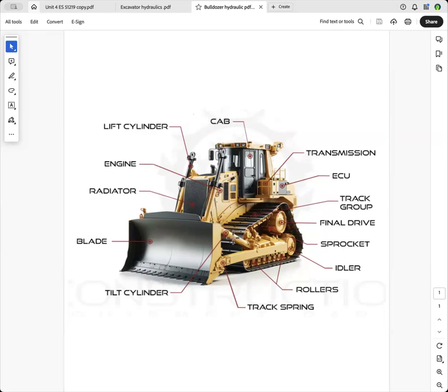There's a hydraulic cylinder here, which tilts the blade. There's a hydraulic cylinder here that does the gouge at the back. And you've got this hydraulic pair of cylinders here, which lift the blade. And it's really important to position these hydraulic cylinders in the correct orientation, because there's one direction of a hydraulic cylinder that is more powerful than the other direction.